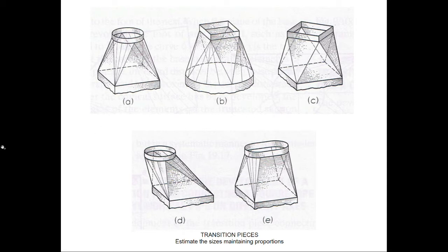Okay, so we're going to start with A, which is 2 circles and a square base, and the project calls for the base to be a solid piece that's shelled out to an 1/8 inch wall thickness. There aren't any dimensions, so you're going to have to use your judgment to be close to the proportions. What we are looking for is that this transition geometry replicates what we see here. The loft command can give you multiple results depending on how you approach it. So let's start with A.